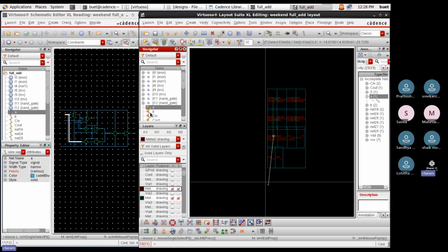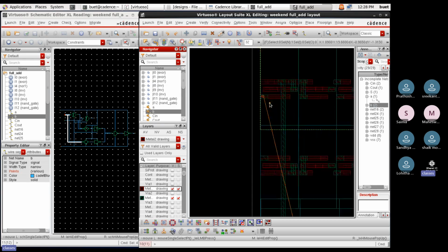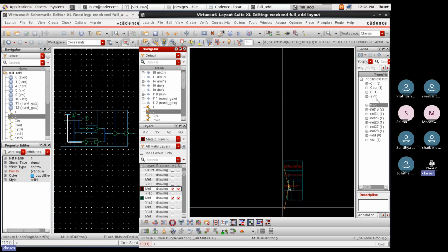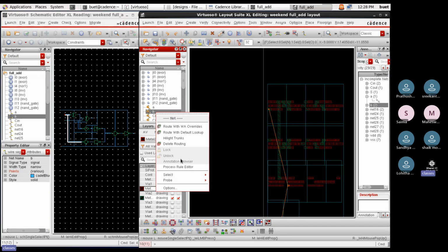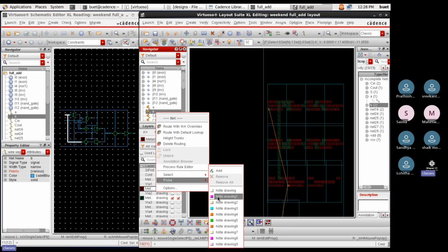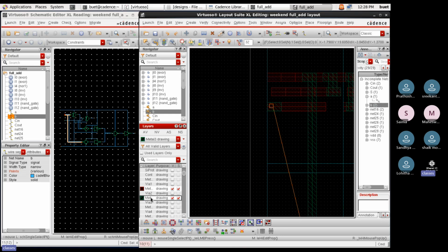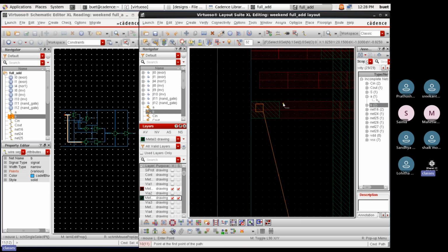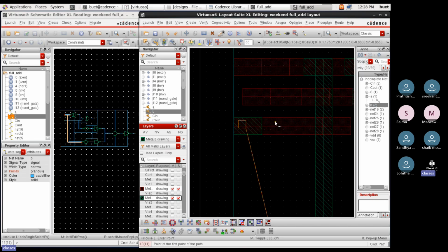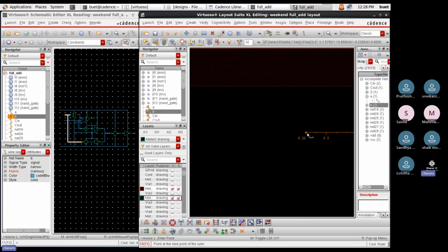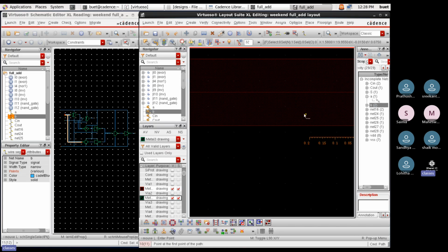Now I will go to the B option, B connection. Now the B connection says that we need to connect this guy from here to this level. Okay, let me probe it and let me make it orange color. Any color you can do. So I will do the metal 3 connection again from here. To do that, I will be drawing a metal connect track from here by keeping a distance of 0.2 micrometer. 0.2 micrometer minimum I will do it from here.